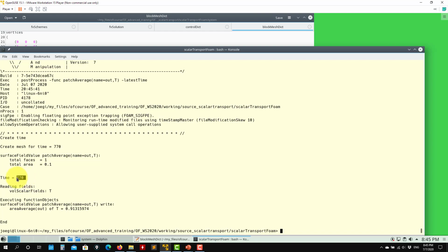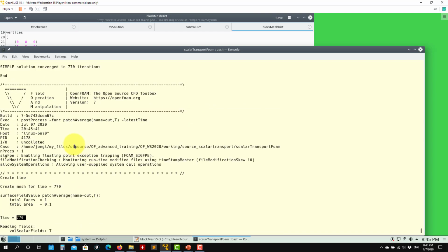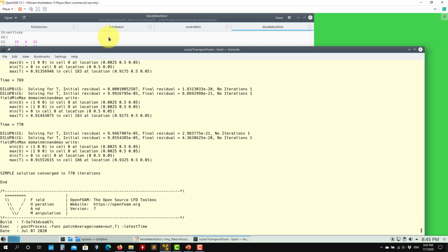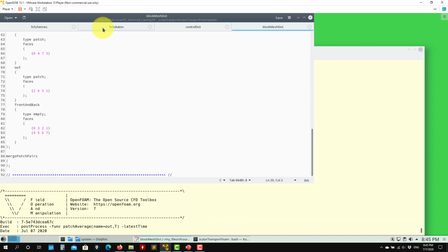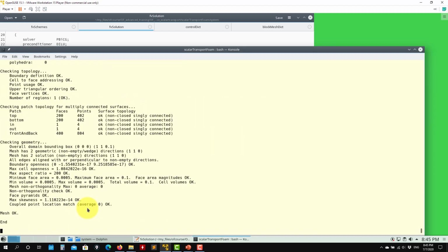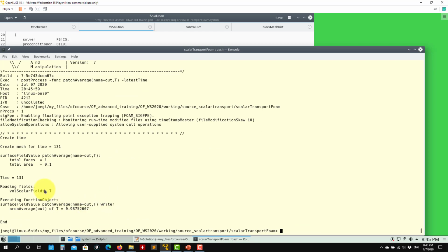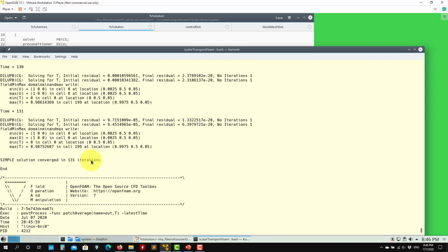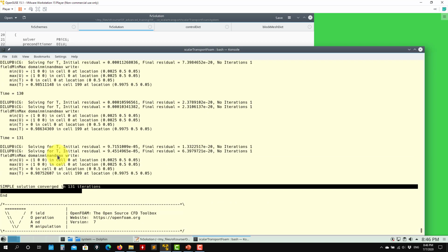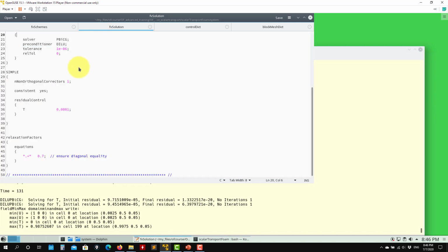So this is 700 iterations, okay? And see that it is still increasing, it hasn't converged yet, but now I can control that by increasing my under-relaxation. Usually 0.7 is a good value, but again, this depends on the problem. But see here that by increasing that, we greatly accelerate the convergence. It's still a little bit far, okay, but we know what is going on.